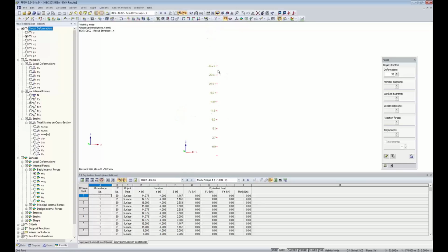And we continue to do so all the way up to the top here, where our top deflection will be 30.2, but the inner story drift will be 30.2 minus 26.4. So again, we'd want to refer to the standard here for those minimum inner story drift requirements. And for our case today, we're meeting those, so drift seems to be not a concern.